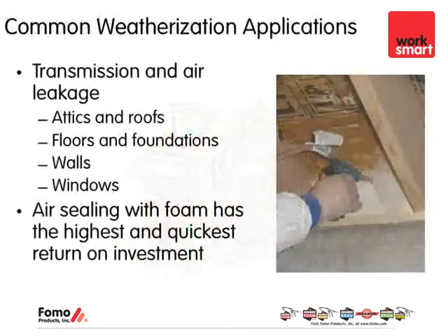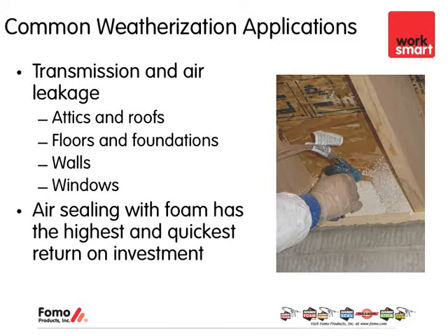Now we want to focus on some common weatherization applications as they relate to the low pressure foams. Transmission and air leakage happen throughout the whole entire house. It happens in attics and roofs, in floors and foundations, in walls, and in windows. The trick here is air sealing.